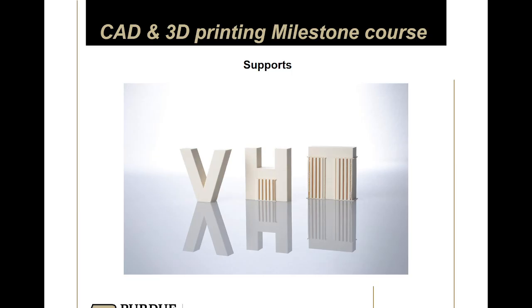Orientation also affects how strong your part is going to be. When it comes to cylindrical shafts, the logical idea to print it for the best quality is printing it straight up and down like this, right? But there are layer lines going all the way up, and if you have something bending it, I don't want to break this final, but you can easily split the layer lines.